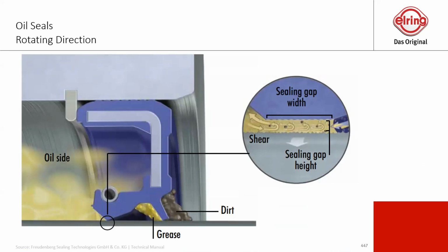That's right the point. So in this case, we need a kind of lubrication between the rubber material and the metal material. That means we need a liquid, any kind of fluid in between. And this is what we're using: the oil from inside as the lubrication between rubber and metal, to avoid any friction, to avoid any burning marks, heat, whatever exists if you rub metal against rubber.